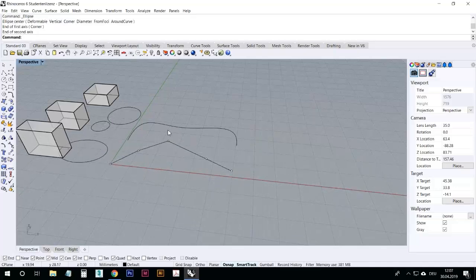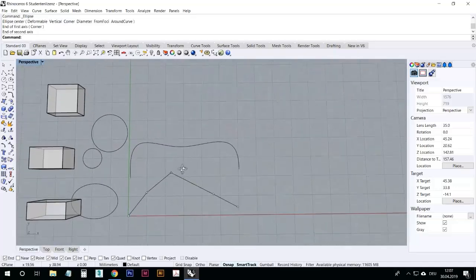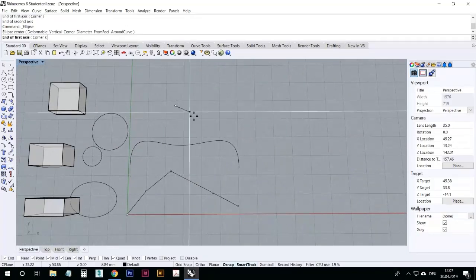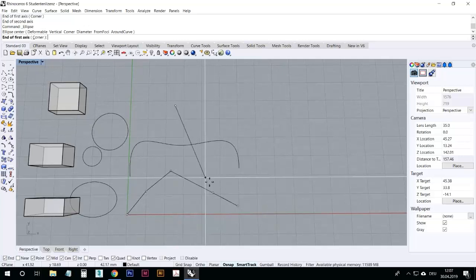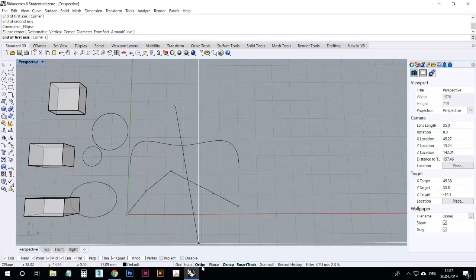Now you notice probably that when I drew, I made a straight line, right? Maybe you want to have an exactly straight line. Then you hold shift, which means you will get straight lines like this. A shift like that can always be there constantly if you choose ortho down here, or in Mac it's another place, along the x-axis and the y-axis here in the workspace.